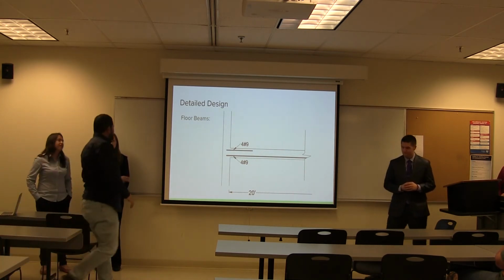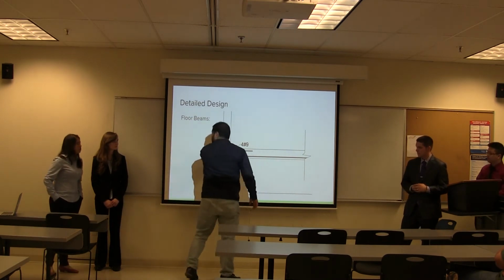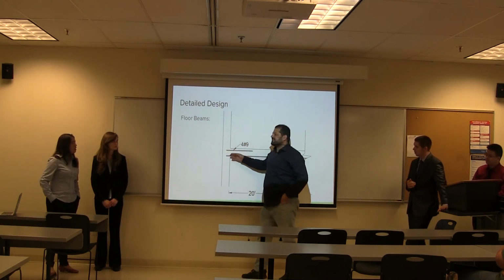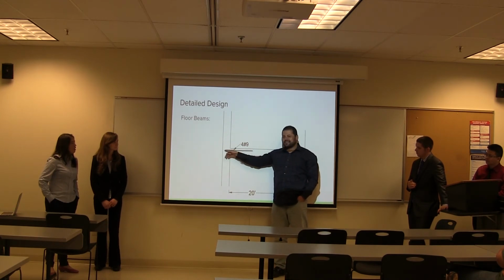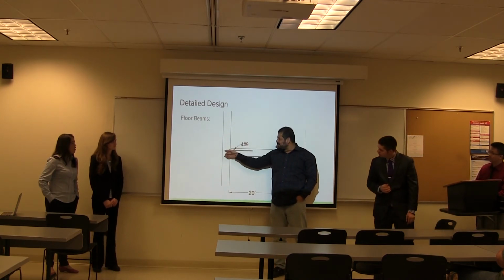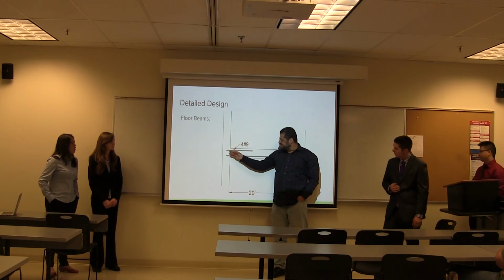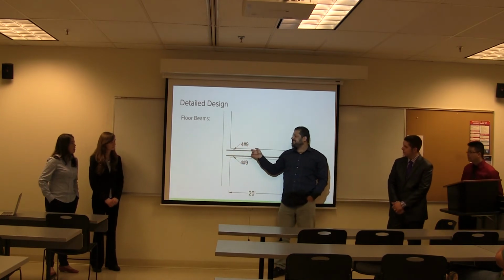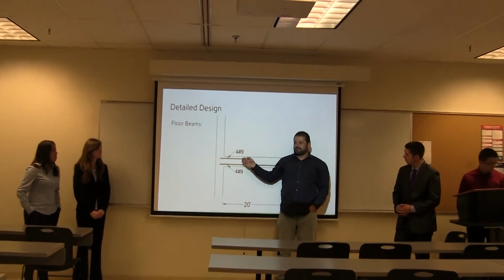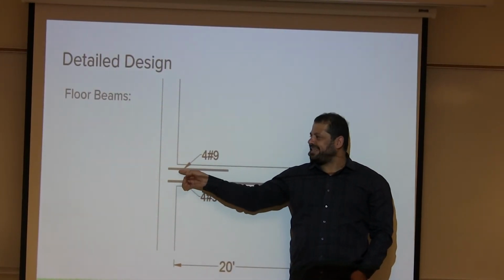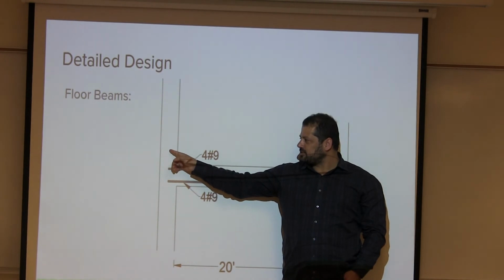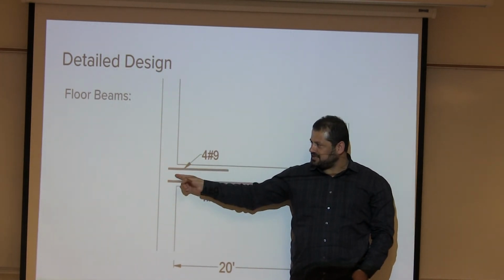Okay, so this is a pin. This detailing cannot give you any fixation. If you want to have this negative moment, this reinforcement must be hooked to develop a fixation here. This detailing will give you a pin. And anyway, you don't need this one, by the way. If you provide this one, it will give you a slight fixation, but not like that. With some hook, you create some kind of fixation here.